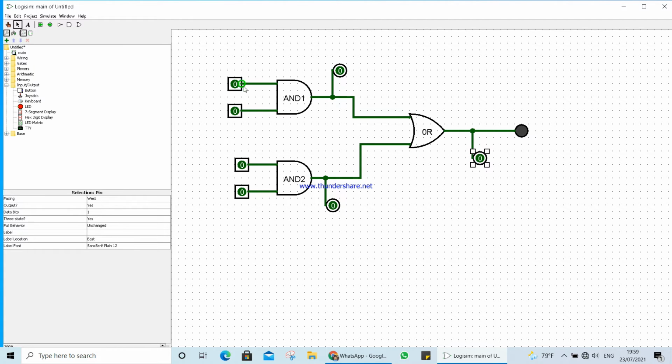So now my logic circuit is almost completed. What I want to do now is simulate this one. I will be checking that the simulation is enabled. Now before clicking you have to change the tool to this hand tool.